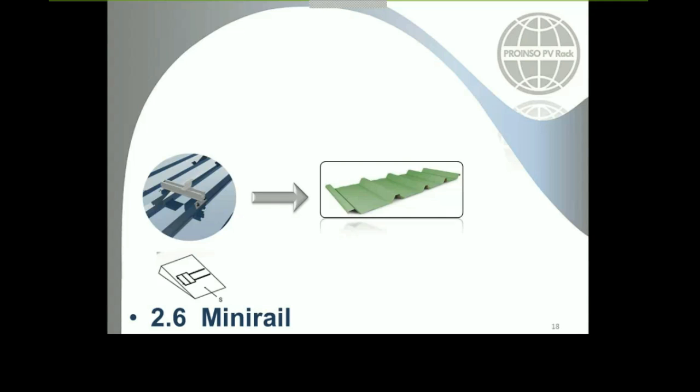We always consider the 2 millimeters one because we have some assumptions in our calculation of the kits, for 120, 150. But imagine that in some areas you have, I don't know, 30 kilometers per hour, or you have no wind loads. If the metal sheet has 1.2 millimeter thickness, you could install it as well.